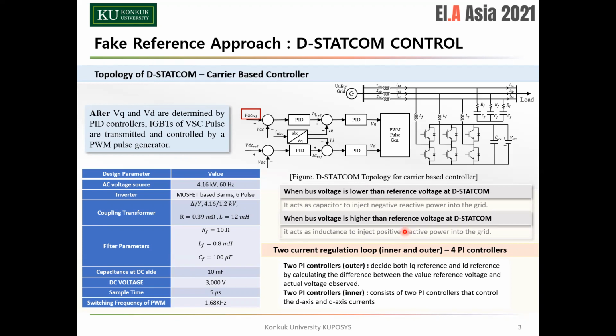Both voltage and current components are obtained from ABC to DQ transformations in the synchronous reference frame, determined by sine or cosine terms provided by the phase-locked loop, PLL. It is then regulated with two separate PI regulators with respect to the reference D-axis and Q-axis currents obtained earlier. Furthermore, RC damped filters are connected at the inverter output, and a capacitor is acting as a DC source for the inverter.